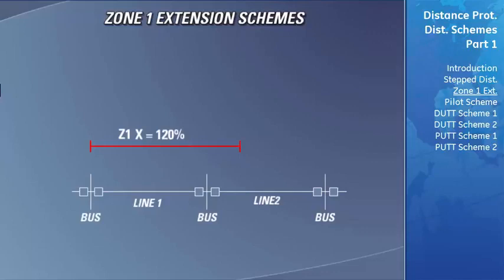With the line reclosed, the D60 will use the standard Zone 1 characteristic and underreach to only protect an area within its own transmission line. If the fault that occurred was a permanent fault and located within the transmission line's newly shortened zone, the D60 will trip and again open the circuit breaker to clear the fault. If the fault was transient in nature, the first occurrence of tripping the line would have removed the fault and transmission of power would resume.